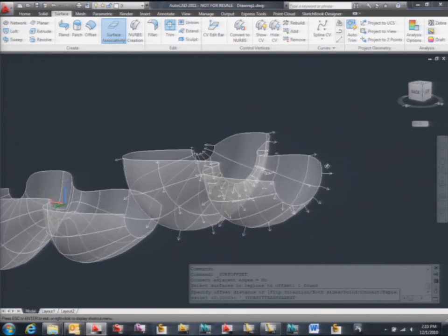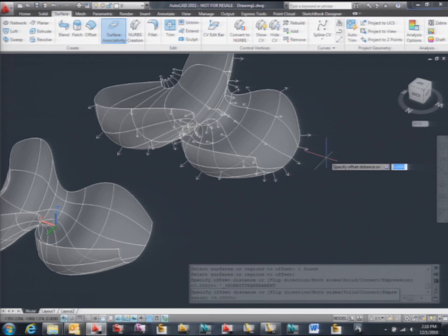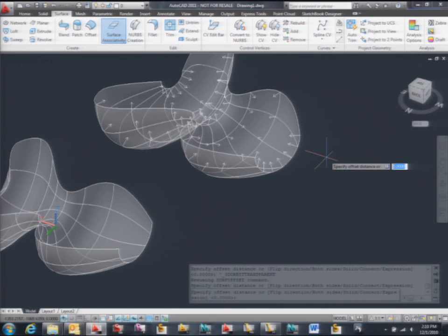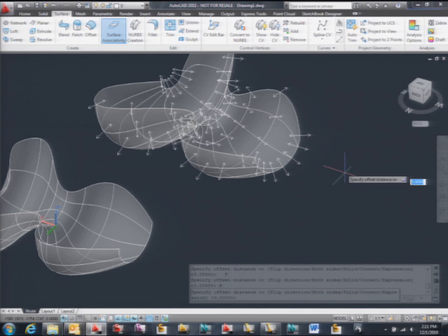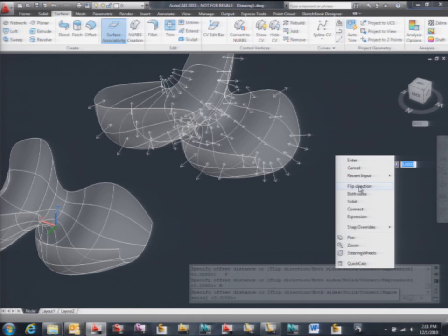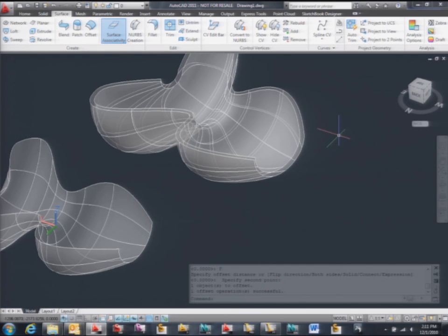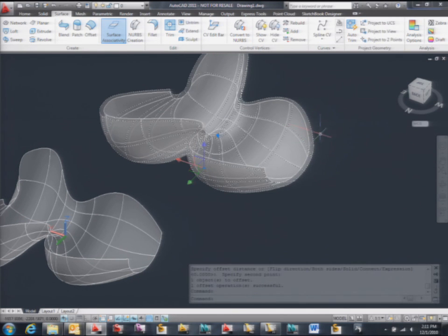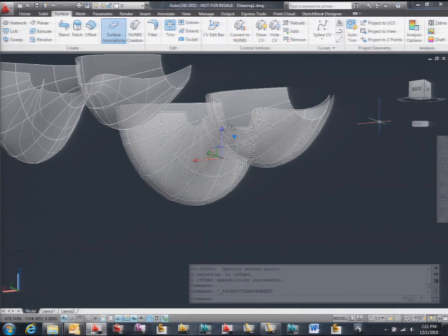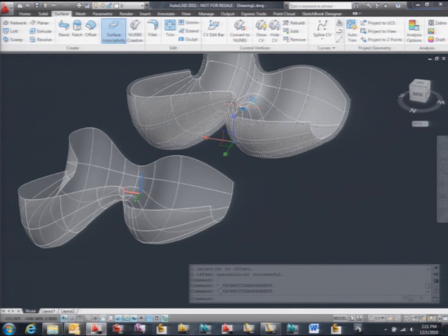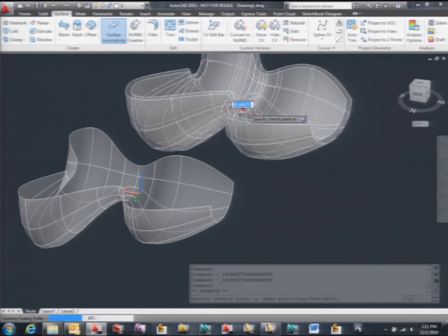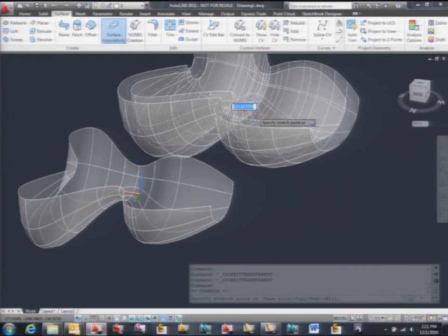So in this case, AutoCAD is telling you, okay, offset is going in that direction. But of course, you can flip it. And you can even do it to both sides at the same time, if you want. And just for the sake of clarity, we'll do it just to the outside. And then I'll define a distance, like as usual. It can be numerical input if you're very accurate, or just any distance. And here you go. You made a second surface, which is an offset. But again, this is an offset, so the offset remembers it's an offset and now allows me to change the distance.